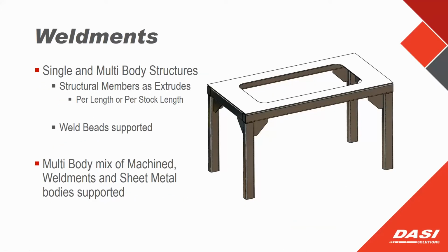Now, weldments are a multi-body component. When we're talking about multi-body specifically, we usually get into sheet metal and weldments as those two processes. But in reality, multi-body can be a mix of three main components, whether it be the sheet metal, the structural members of the weldments, and machined components, which in this case, we have a sheet metal top, could be sheet metal gussets, those could also be machined, and then we have these structural extruded members on the legs of this particular part.